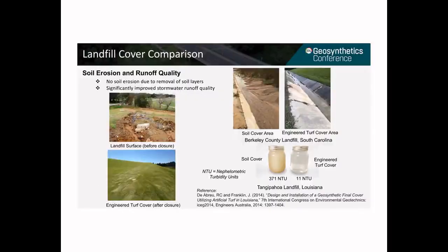A direct result of removing soil layers is improvement of runoff quality, because there is no soil for erosion except for the thin layer of sand infill that has minimal potential for movement. Therefore, soil erosion is no longer an issue and stormwater runoff from the landfill becomes virtually clean.